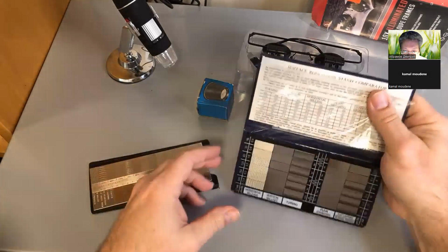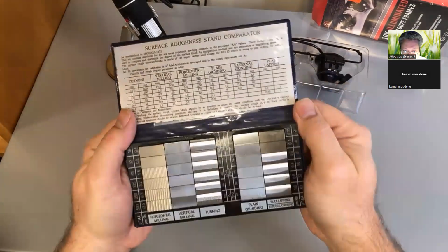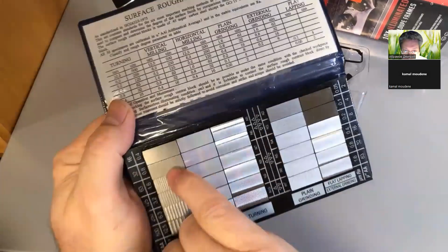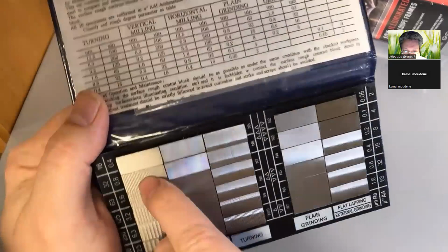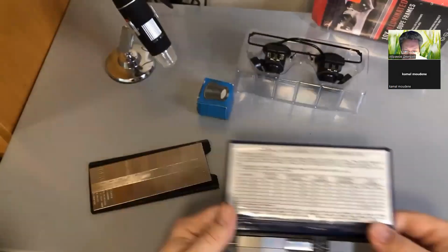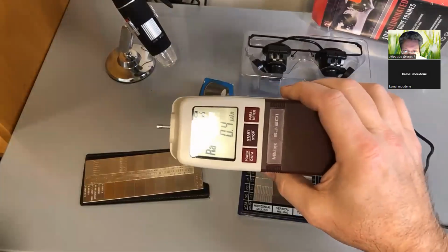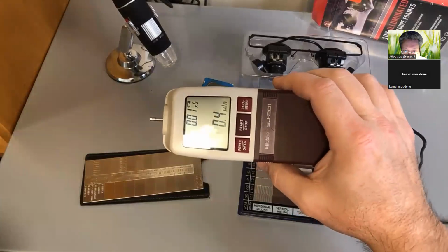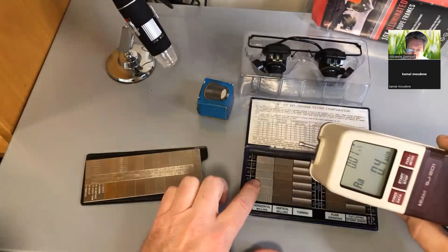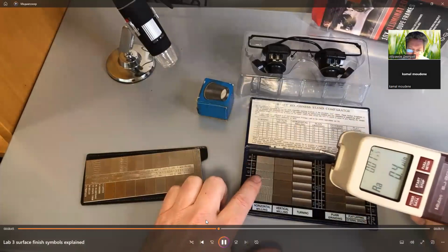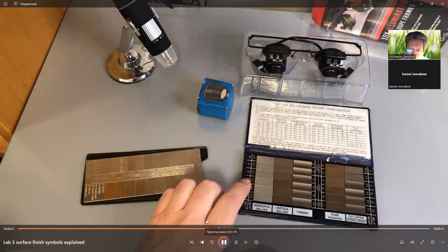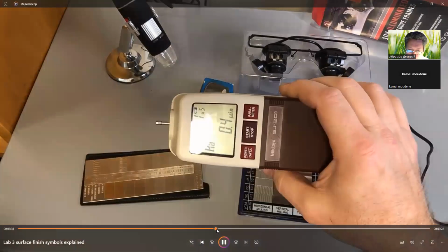This visual comparator here, if you look really closely right here, there's actually a hair stuck inside of this sample. How I know this is because I ran the surface roughness tester over top, and I wasn't getting an accurate reading for what the actual specimen was saying. Now, that doesn't mean that it's out. It just means how I know this is.